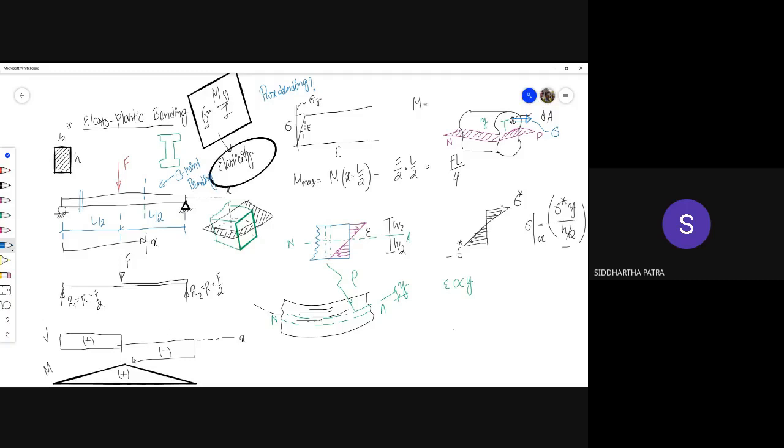And if you really think about it, if you really think that this force F over here happens across a finite area, that means the shear force would be changing linearly in this region. It's not a step, it's a gradual change, and somewhere in the middle it would intersect with the x-axis, or basically the shear force would be 0. So the very tip that you're looking at, that's where pure bending is happening.